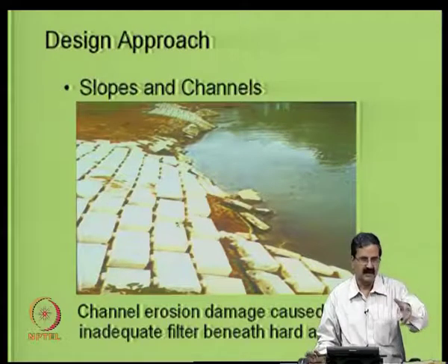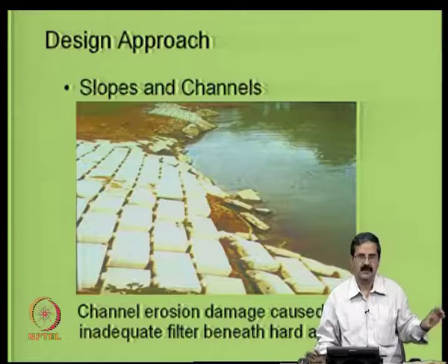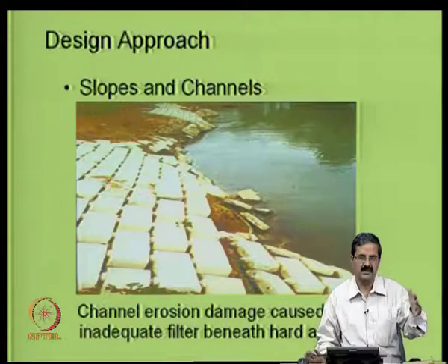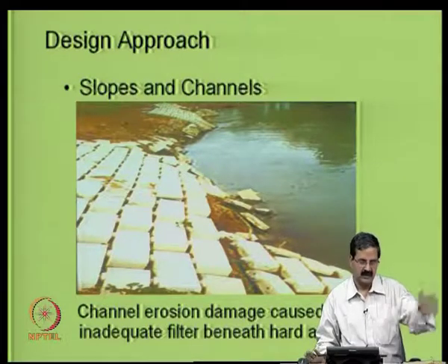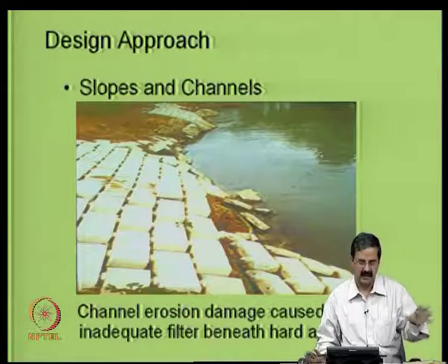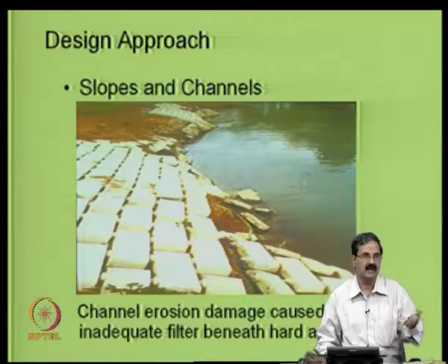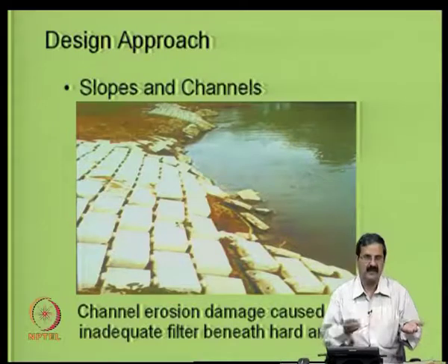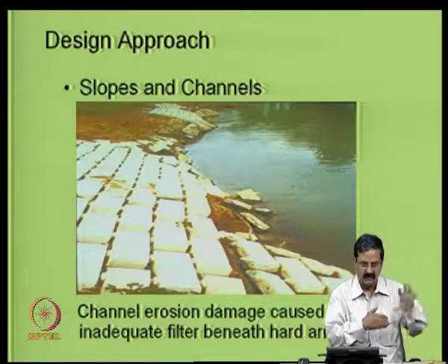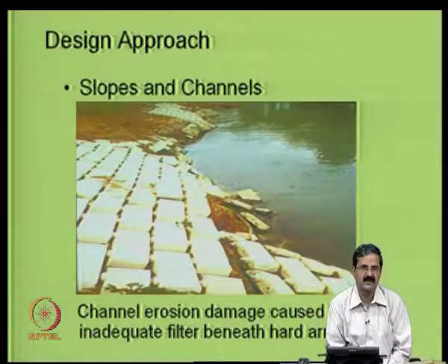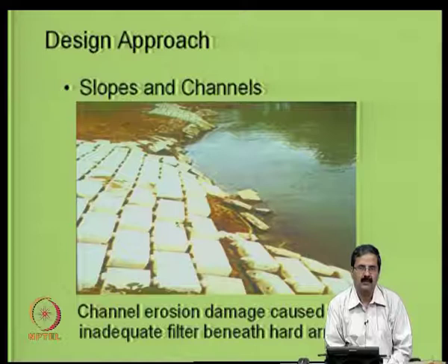In some places, all the retaining walls got overturned, because the retaining wall didn't have proper drainage, and there was a serious issue there. Because of this, the base of the retaining wall also gets saturated, and erosion can come. The soil is under saturated conditions now, and the effective stress is very low. It tries to come out, and when it tries to come out, the retaining wall can fail. The bearing capacity of the soil below the retaining wall is low, so it collapses.